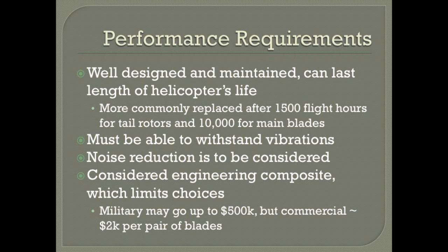Another factor of importance is the ability of the blades to attenuate vibrations. Helicopters have a limited capacity to attenuate vibrations in flight, and thus a reduction in the blades is a significant benefit. Another factor is the noise produced by the blades themselves. As most helicopters operate in civilian areas, the amount of noise pollution generated is a significant byproduct. Lastly, the application has cost implications for the materials to be used.